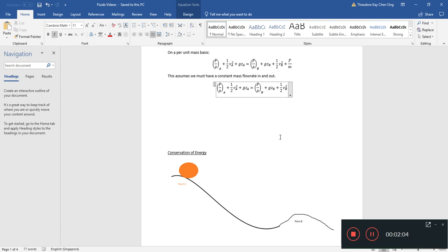Now in the actual derivation of Bernoulli's equation, there will be lots of other things we have to consider, for example, streamlines and how fluid is flowing along the same streamline. But in general, as long as our energy equation satisfies that it's incompressible, or there's the same mass flow rate in and out, and the frictional forces per mass are basically negligible, we can use this equation.